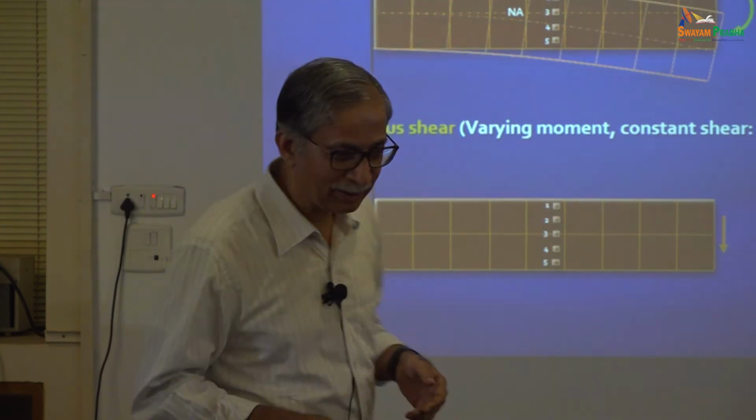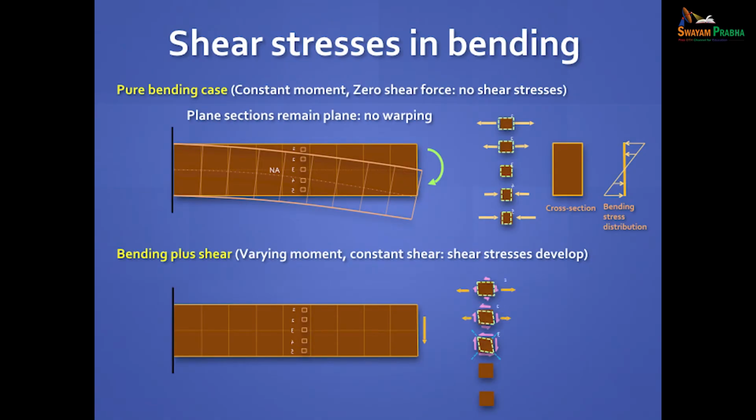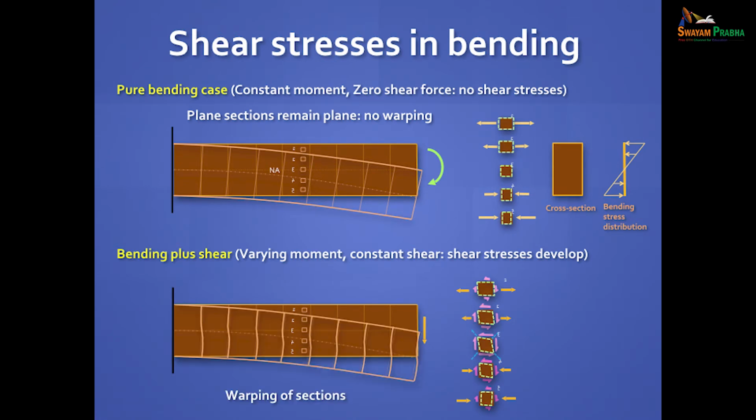Okay, it likes to distort the section, and the distortion is less here progressively, and here it is least. Here at this, it's still not zero because we didn't take at the top. At the top, it's going to be zero. And similarly at the bottom, you'll have a distortion like this. So that's the difference between this behavior and this behavior. And what happens is you'll have warping of the section, slight warping. Is it clear? All right. The shear is constant here. So the shear strain is constant everywhere in this particular example. All right. And this is how the shear stress vary.